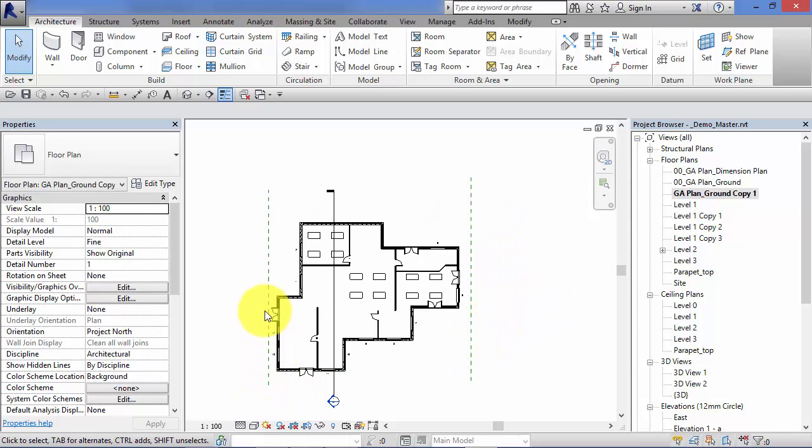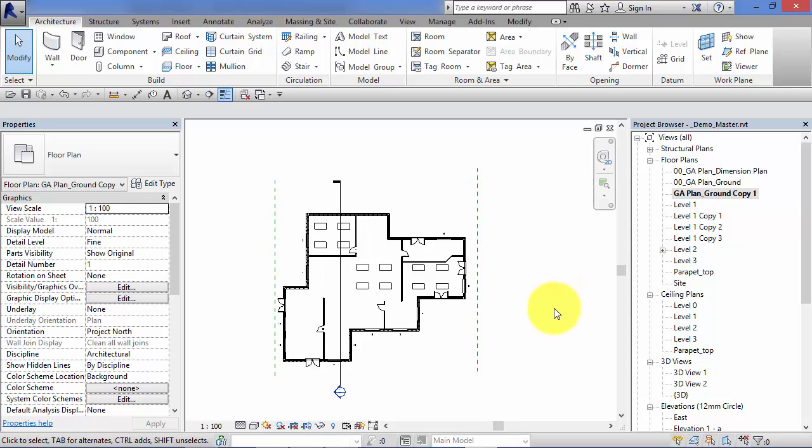So although we can't see the roof in this plan, it's actually above the cut plane here, we can see the reference planes which control the start and end of that extrusion. So that's probably the more common use of reference planes, is to actually control geometry. It doesn't just have to be roofs, it can be any sort of 3D geometry. We can actually set up these reference planes which act basically as work planes on which to set out our geometry.